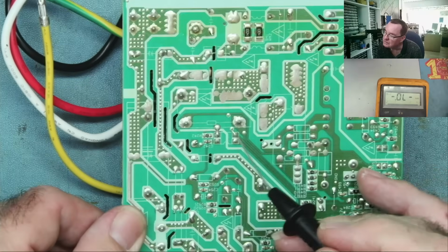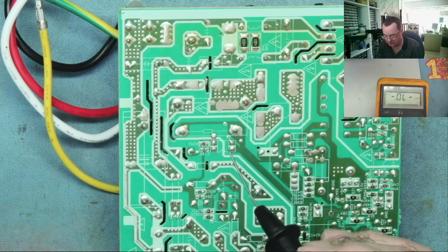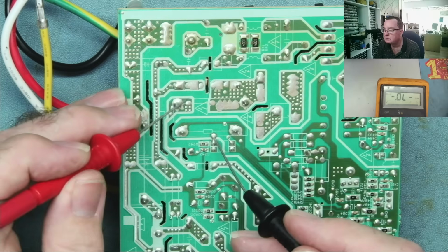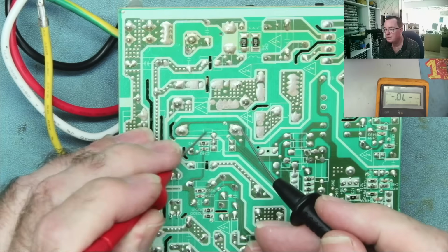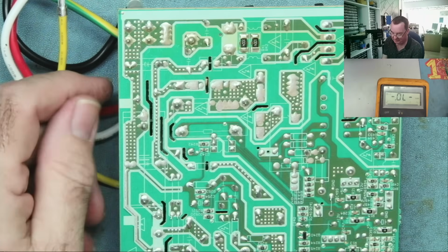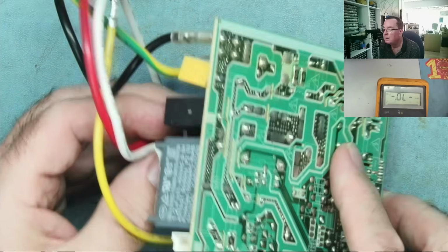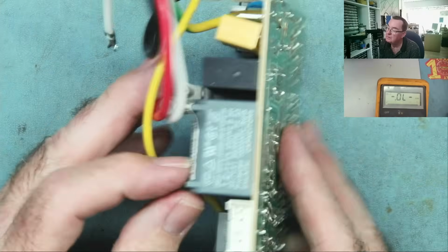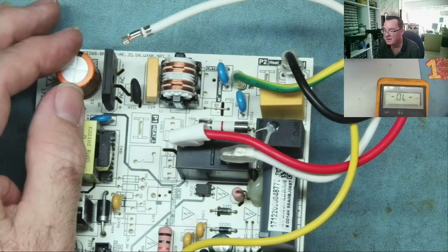What I can see is that's an optoisolator. Yeah, but it doesn't go to here, so no connection to there. Okay, so in this case, to test that relay, I need to take it out. Let me look at the other one. So there's another relay here. No, that's a capacitor. Okay, so there's only one relay. So let's just take the relay off the circuit and let's just check it.